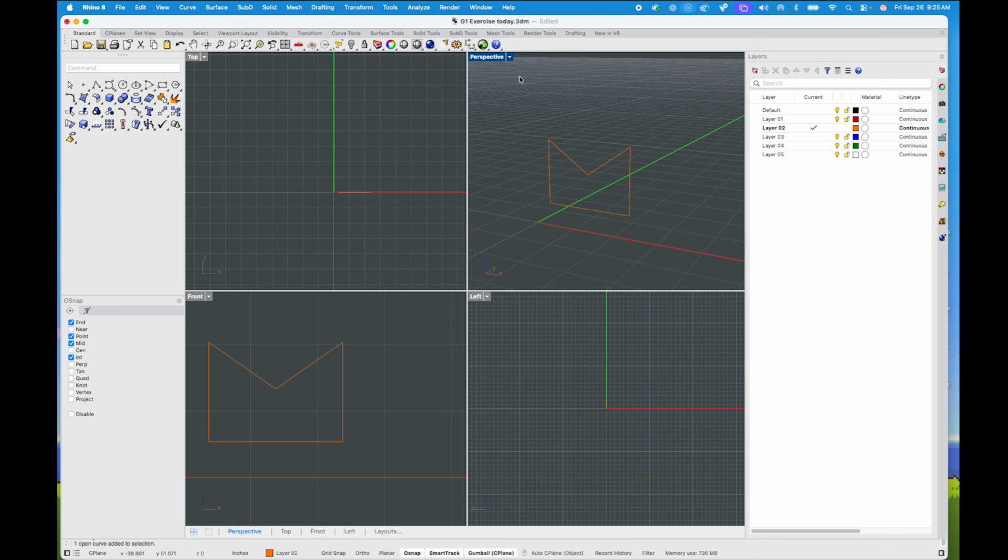And to be fair, I can tell that this object itself is not exactly complex, and it actually just extrudes a thickness, right? I just need a thickness to it. So in my case, I'll take the whole thing, and I want to join them because, well, right now, they're just kind of separate lines, right? I can click on each one, and they're all separate. So quite intuitively, I just want to type in join, enter, and when I click on it, the whole thing is together, right? You'll see there's those points I was looking for, right? And of course, I can move those points as necessary, right, to maybe dial in the object.